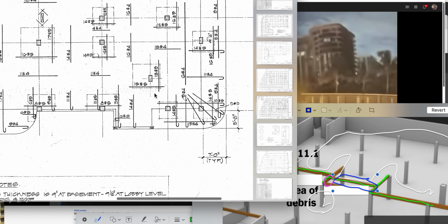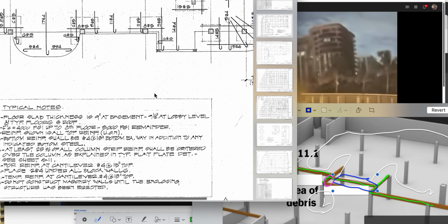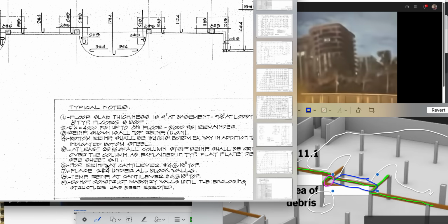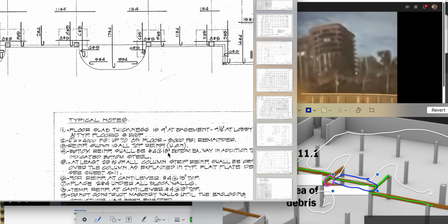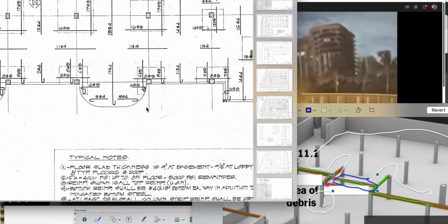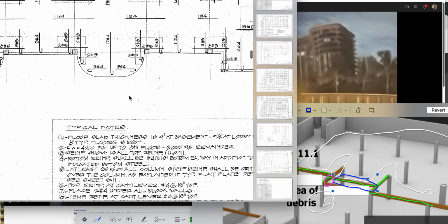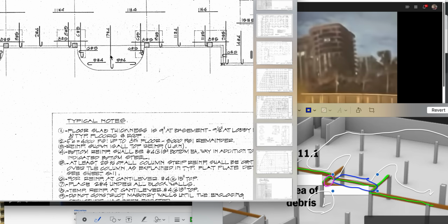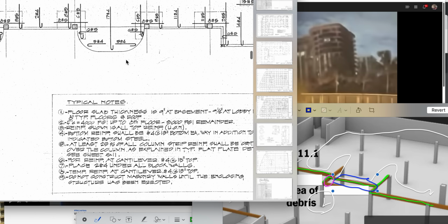And the center line is, as I keep saying, I think I found 13 inches, something weird. 13-inch rule. Let's see if it's down here. For reinforcement at cantilevers, 13-inch on top, centers on top. Okay, yeah, that's the 13-inch on center. That's the cantilever. Okay. Temperature reinforcement steel at cantilever. All right, that's temperature, same. So 6 and 8 appear to be the same note.